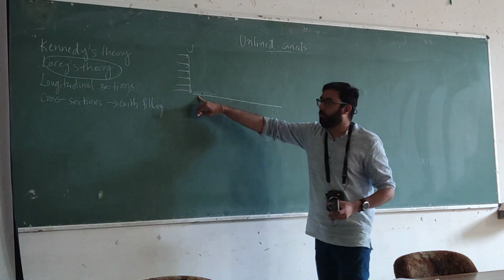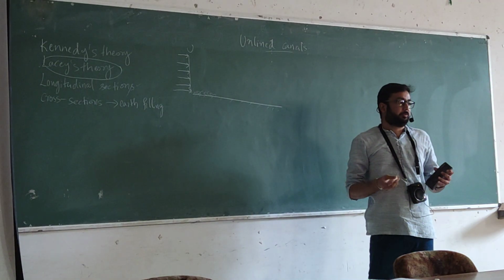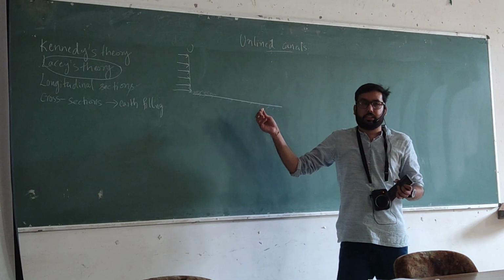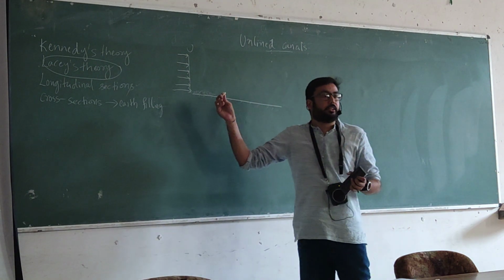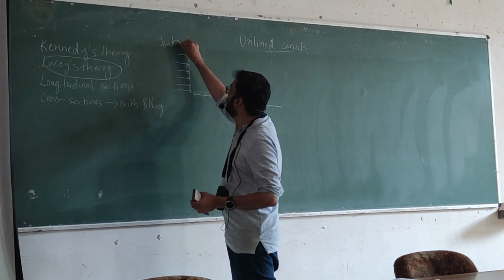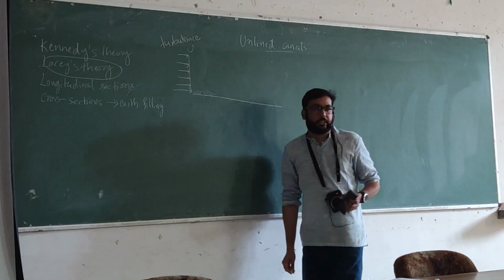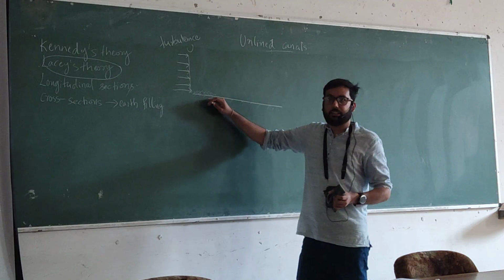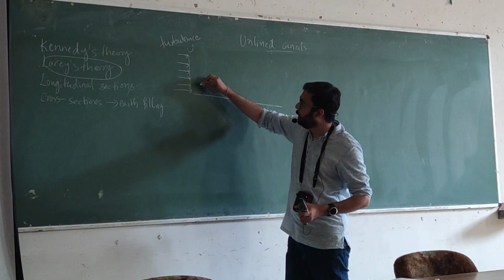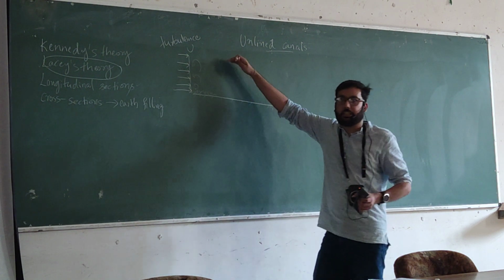Now what would be the impact of these sediments on this distribution? So it would provide resistance and, yes, make the flow non-uniform. So you have heard of turbulence, right? So how does turbulence get generated in this? Because of these particles, you get small rotations or eddies, and they keep growing in the vertical direction.